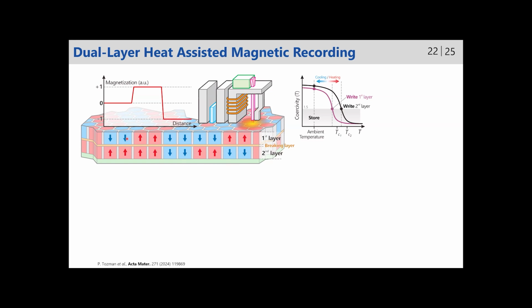For example, when we have down magnetization for the top and up magnetization for the bottom, and another option when both in one direction, both in opposite. All this gives different level for magnetization and different stray field for the sensor when we read the signal. So it gives a chance for multi-layer recording.